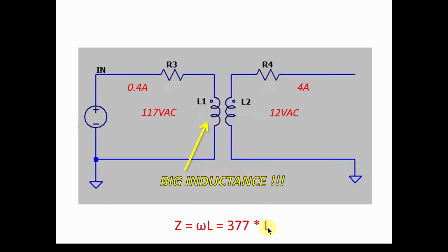So now we're starting to say, if I make a measurement of this transformer at no load, I better see an inductance at 60 hertz that is significantly bigger than 1 Henry. So now we're starting to see what we can expect here.